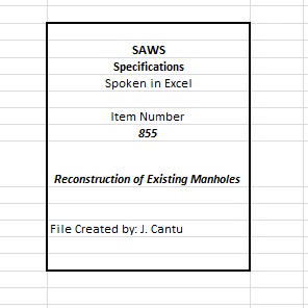855.4 Materials. 1. All reconstructed manholes shall be watertight and coated with a SAWS-approved sewer coating. See SAWS APL. 2. Existing monolithic manholes are not to be reconstructed, but replaced under specification item number 852, Sanitary Sewer Manholes, or specification item number 850, Polymer Concrete Sanitary Sewer Structures. 3. Precast reinforced concrete manhole sections. Precast reinforced concrete manhole sections shall conform to the requirements of ASTM designation